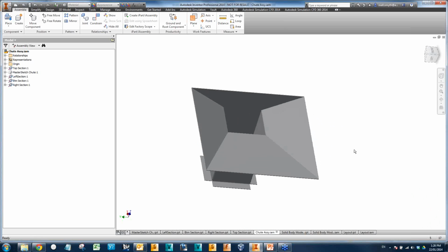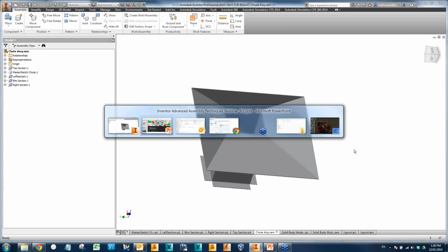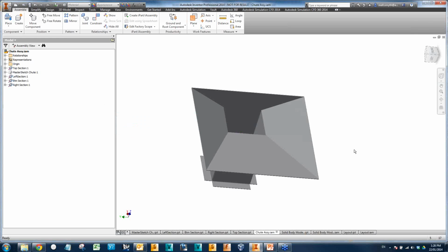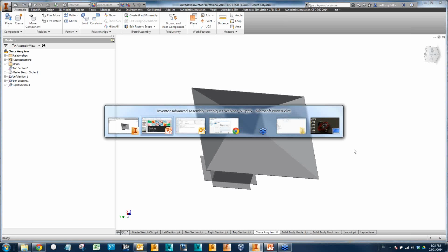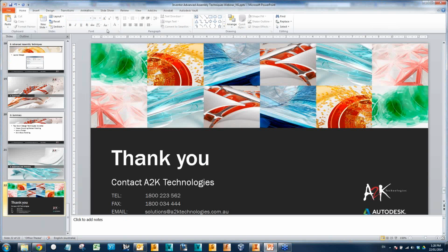So you could create it as a single part and create cuts. It would be a pretty weird flat pattern. But I guess the question is, can you find a sheet big enough as well? So yeah, for sure, you could create it as one sheet, but I'm not too sure how the flat pattern would look, and create a rip. So that's an option for lofted shapes and so on. But the case is, can you get someone to cut that flat pattern, and can you get a sheet big enough for it? So the example I looked at was creating 4 individual parts. So if you can create a flat pattern from one piece, then I guess that would be the way to go.